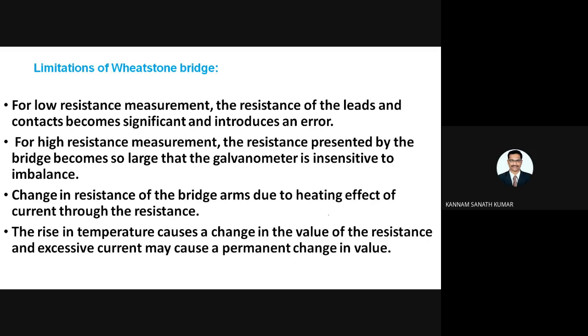Limitations. So there will be an error. During measurement of low resistance, the lead contact resistance becomes significant, so it introduces some error. And if you want to make a high resistance measurement, the bridge becomes unbalanced. When the bridge is unbalanced, the galvanometer is insensitive.